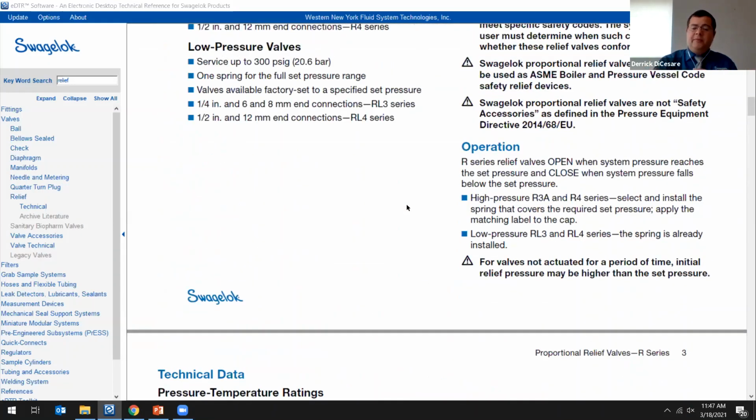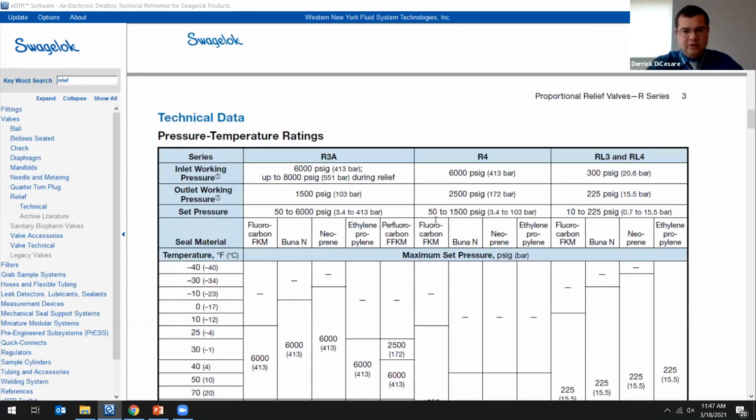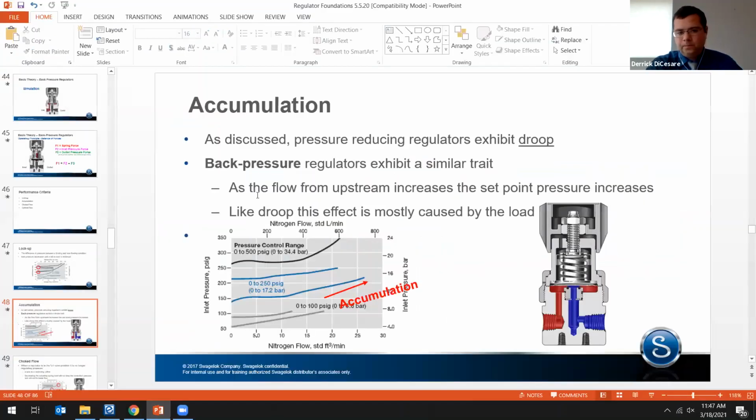So yeah, relief valve, back pressure regulator, essentially doing the same thing. We have used back pressure regulators in a relief application because of the low pressure nature of it. Relief valves typically don't go very low. Ours are kind of limited to 10 psi. If you needed a relief pressure at 2 or 3, you can't use a relief valve. You've got to go to a back pressure regulator, something that's going to be more sensitive to your pressure changes. Good question. Thank you.